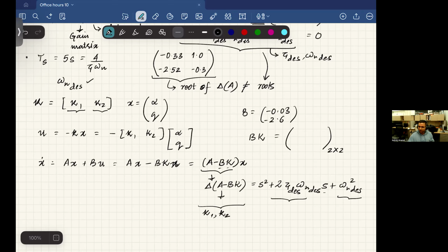So has this been discussed in class, how do you actually implement control? Yeah, a little bit. Basically, we put in electrical amplifiers. There will be a sensor which is reading the angle of attack. There will be a sensor which is reading the Q. What is Q? Q is the pitch rate. So some sensor measures the pitch rate, some sensor measures the angle of attack,